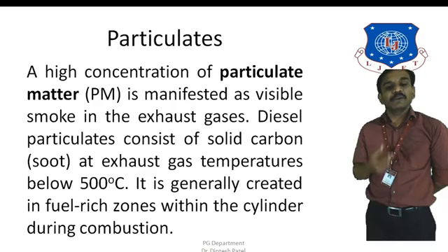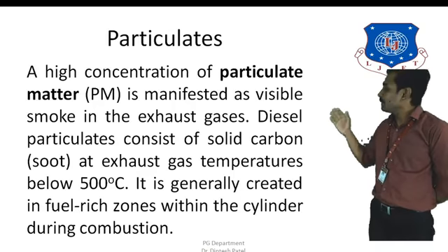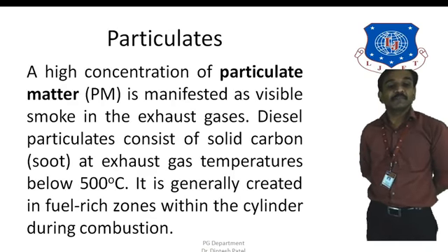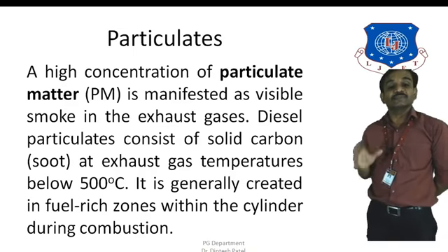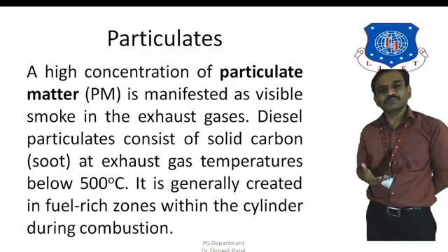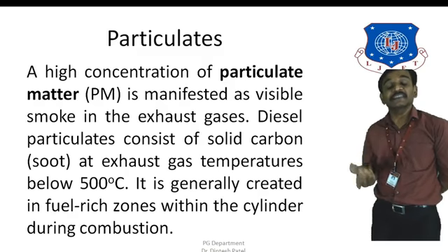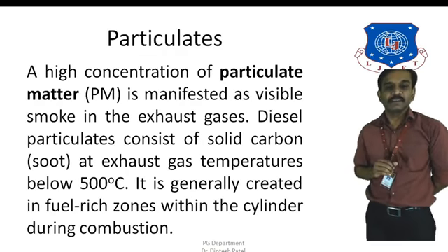Diesel particulates mostly consist of solid carbon, also known as soot, at exhaust temperatures below 500 degrees Celsius. Particulates are also created at a higher level especially during the rich mixture, because there is not enough oxygen to burn the fuel completely.